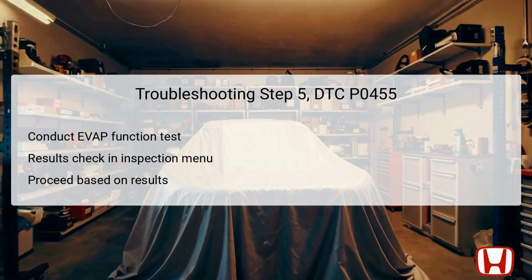This test evaluates the functionality and integrity of the EVAP system components in a controlled manner. It's essential to closely monitor the results. If the test results are satisfactory and no issues are reported, it indicates that the system is functioning as intended. However, if the results indicate a failure, further investigation is required. Should the test return an OK status, this may suggest an intermittent issue, prompting a check for loose connections or poor terminal contacts in related components.